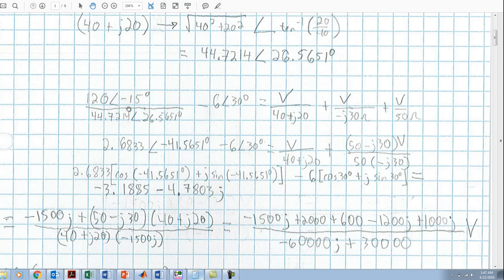And so now we have that in here, and we are dividing those two phasors, and we're subtracting off this other phasor, and that is going to equal V over these various complex impedances. And so we can go ahead and divide these two phasors, just divide the amplitudes here and subtract the angles from each other.